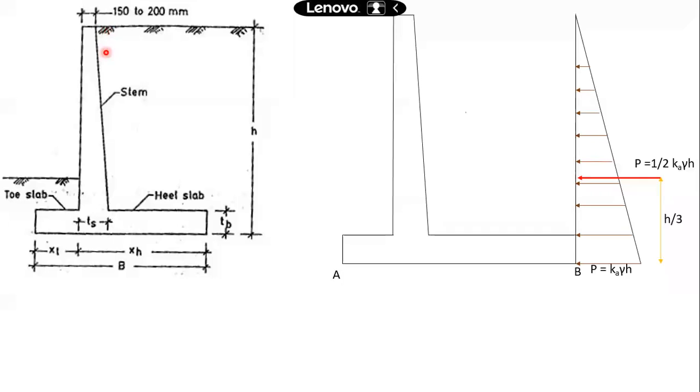Now, from the stability point of view, reinforced concrete retaining walls maintain stability in a different way. Weight components will be coming there, but I don't want to discuss that stability point over here. This sloping portion is also used in the gravity type of retaining wall. In that case, the base is broadened, so that will help in maintaining the stability. When you move towards the base, a larger base is required, and that helps us maintain stability. Here also it is useful to some extent.